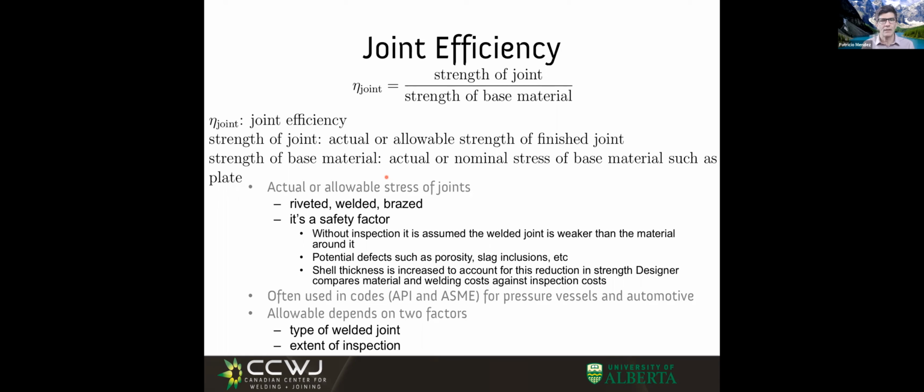In this province, in which we use lots of things according to ASME, for us, very seldom do you break at the weld metal or at the heat affected zone. Typically our welds are stronger than the base metal. But in places like the automotive industry, and some other industries, they use this concept of joint efficiency.